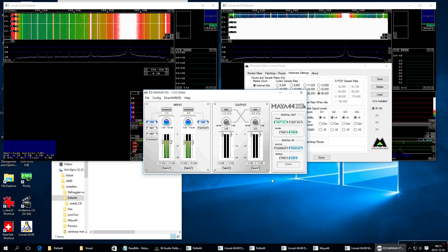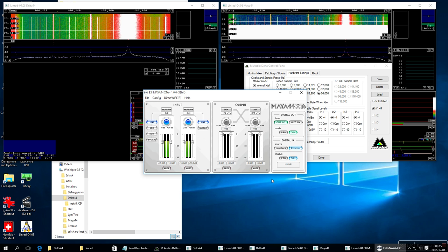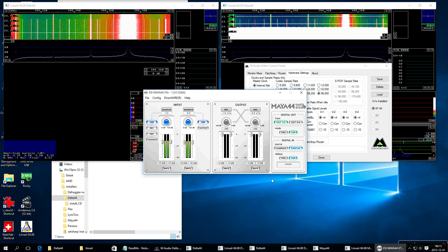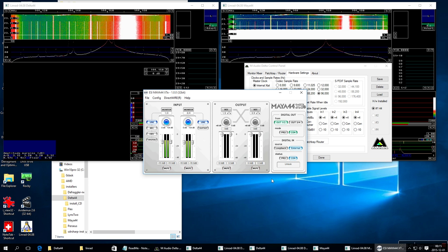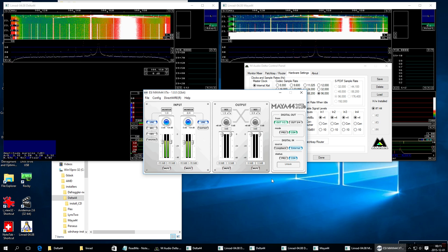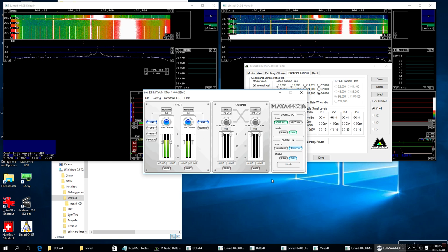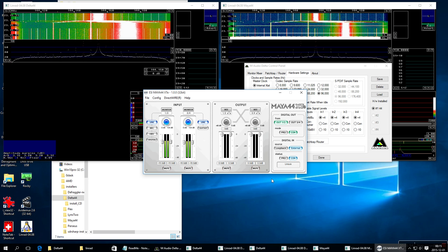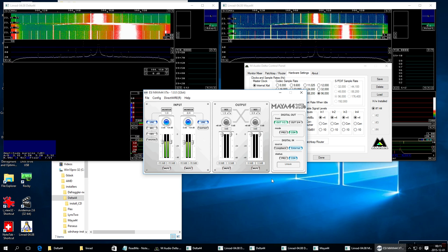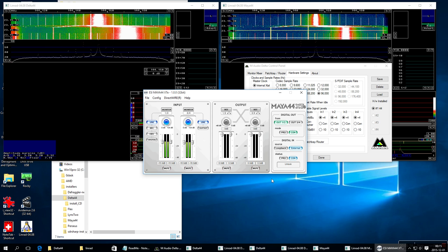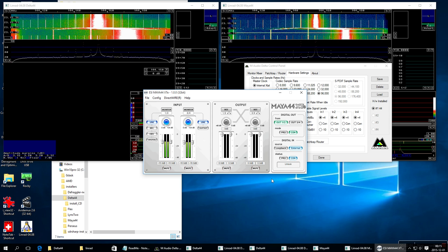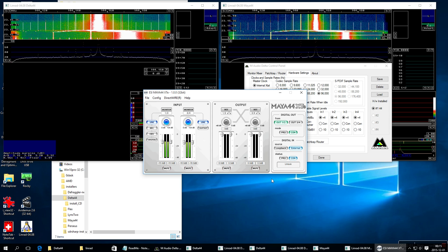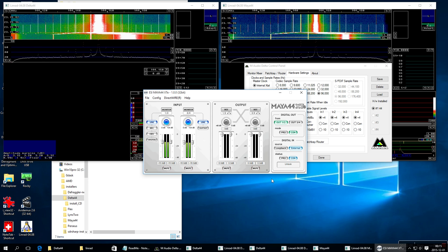And then I will reduce the level, and it is clever to go to a frequency closer to the center, because here you can see there is a lot of distortion, so this level is actually too high. This could be a suitable maximum signal to get out from the IQ Plus.